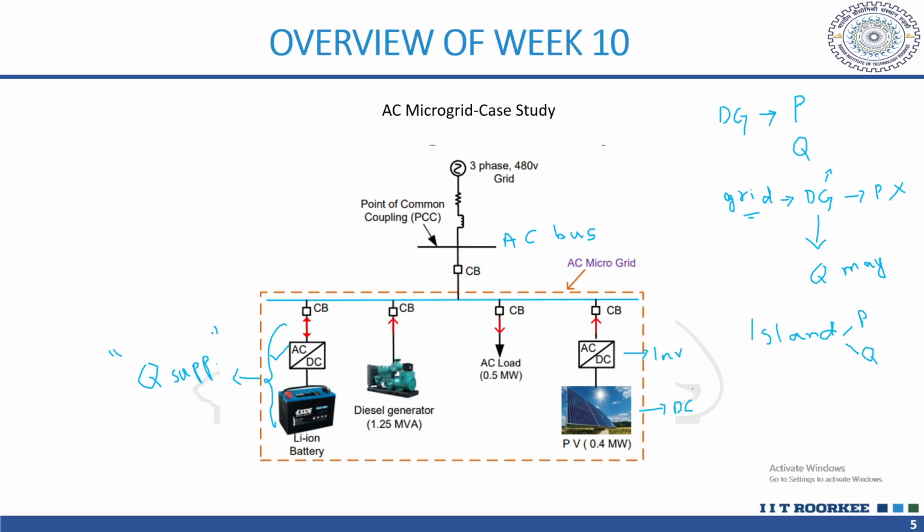And also, we had studied about grid forming, grid following, and grid supporting converters, right? So if we don't have a grid forming inverter, basically this grid forming is in research state. In actual practice, what we are having is majorly grid following.